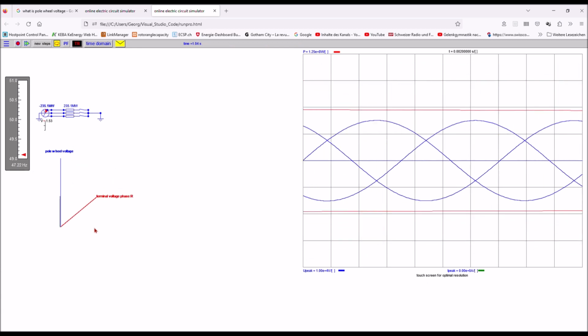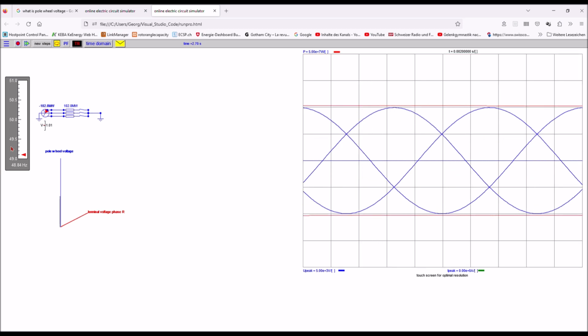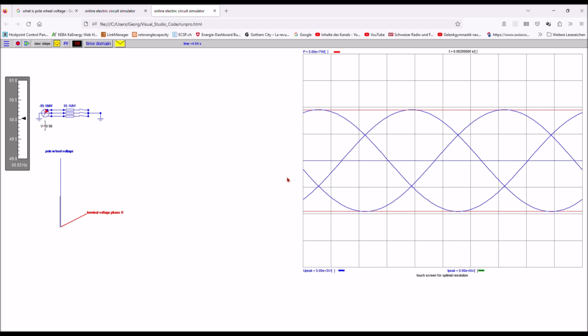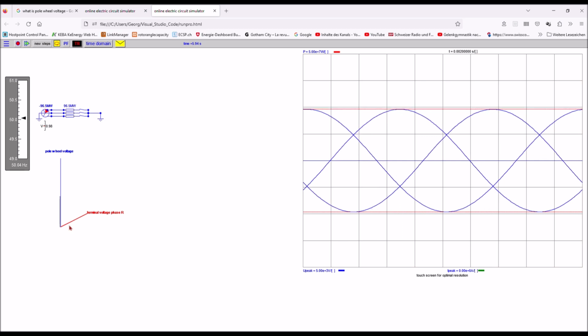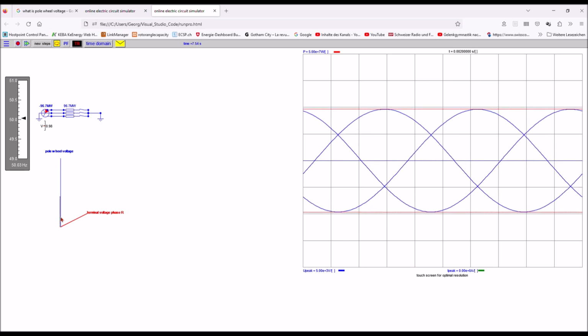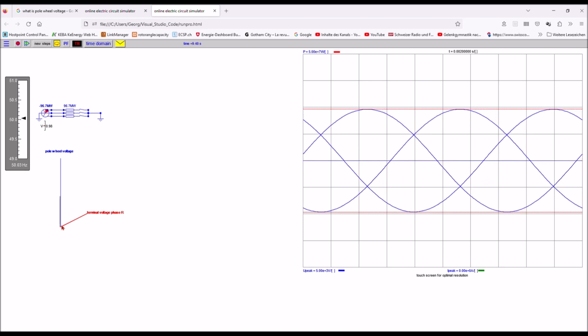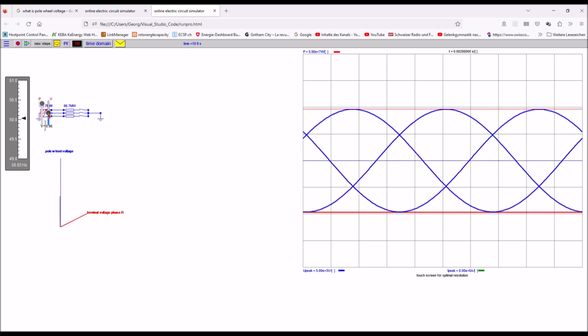The red arrow is the terminal voltage of the generator. Let's now increase the torque of the generator to 100%, so we achieve frequency stability. Again, the red arrow is the terminal voltage of the generator. The black arrow corresponds to 1 pu or nominal pole wheel voltage. The blue arrow is the adjusted pole wheel voltage enabling the terminal voltage at given load.